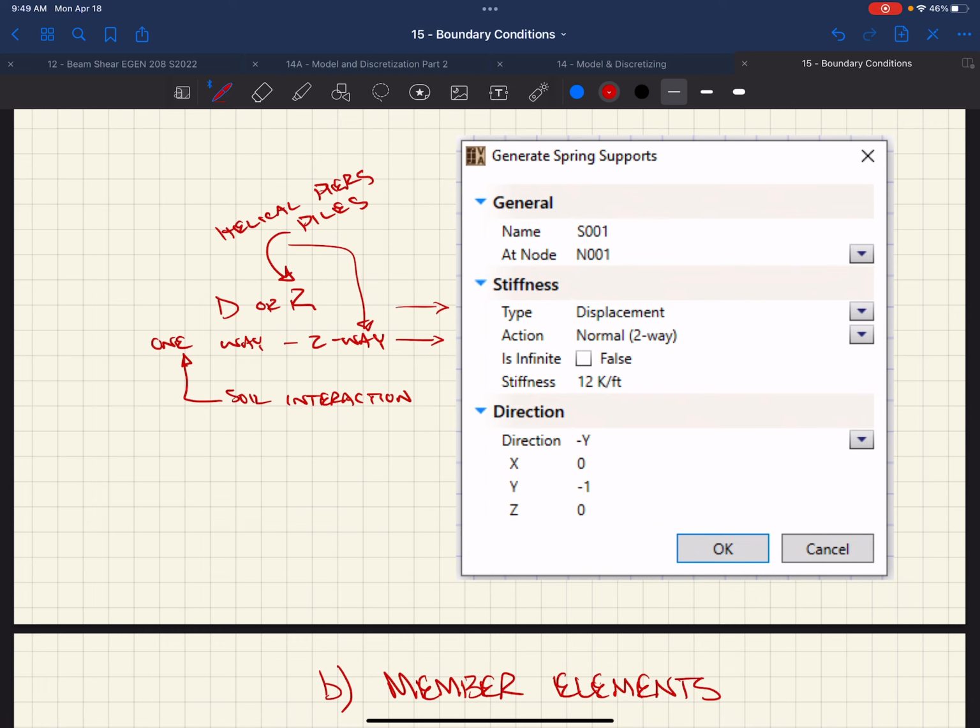It's a shit place, isn't it? Yeah, there's bentonite, so it's expansive soil. If it gets wet, there's a layer underneath the ground that's like 30 feet deep. So you can either over excavate and get rid of all of that and then build back up, super expensive, or you just put your house on stilts, right? And so that's what the helicals do. So all of those houses are generally on stilts.